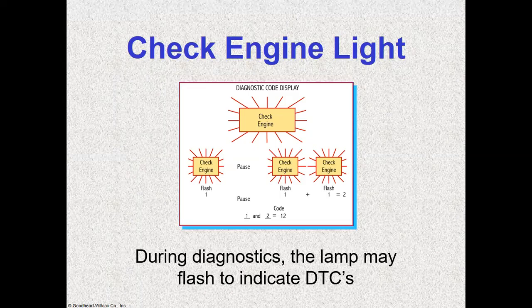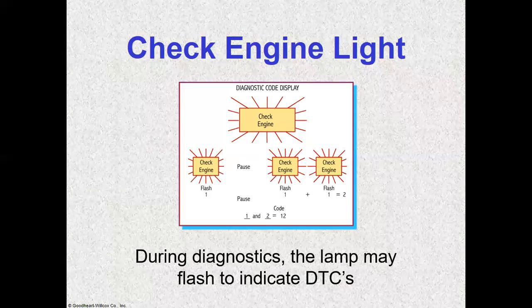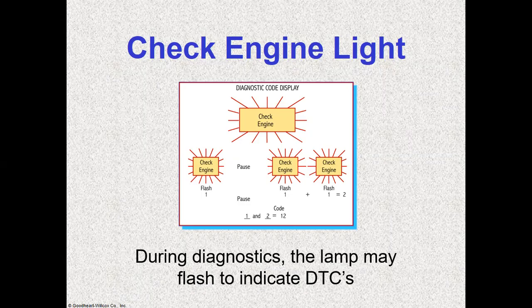If it flashes 3 times without a pause, it's 3. One flash would count as 1. So you put the 1 and the 2 together, and in this case we get 12. One long flash would be like 10, so each long flash counts as 10. If we have two long flashes, flash, pause, flash, pause, and then flash, flash, we would classify that as 22.